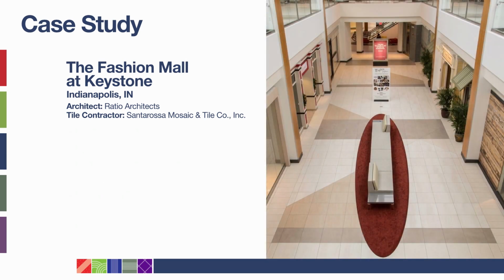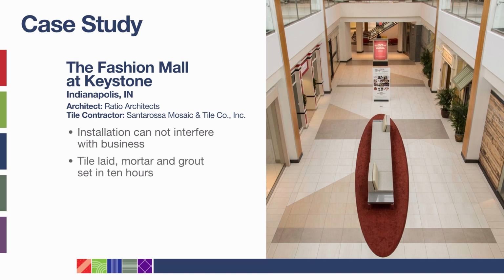The Keystone project presented its installers a particular challenge. The entire installation had to be completed without interrupting regular business. This meant that the installer had to have the tile laid, mortar set, and grout applied in just 10 hours while the mall was closed. Because of this strict time constraint, the installer relied on fast-setting mortar made specifically for large format tile. It provided non-sag, non-slump characteristics and exceeded ANSI A118.4 and A118.11 shear bond specifications.